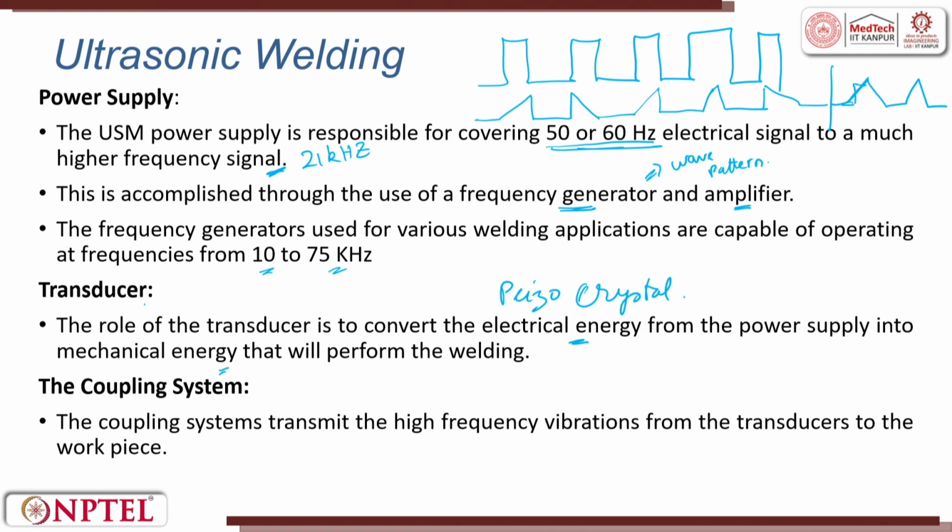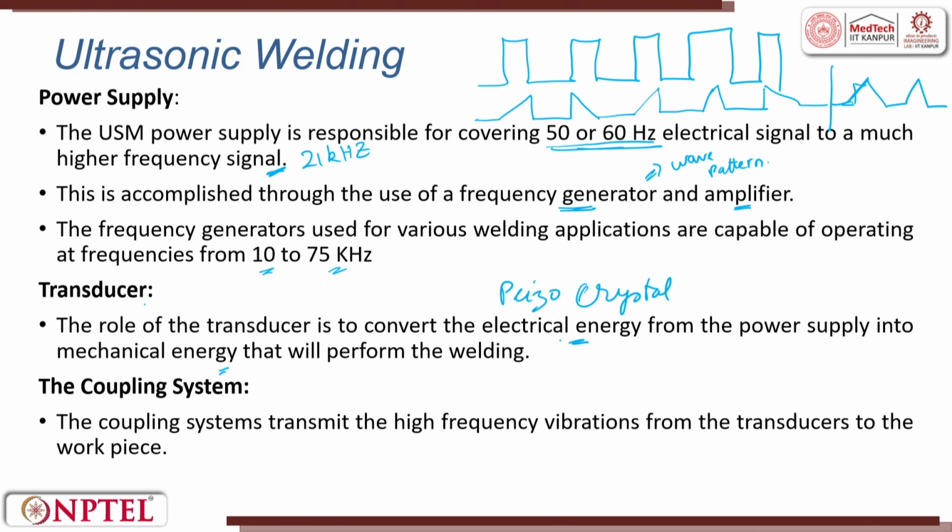The piezo crystal which is there. So, you apply voltage, it expands. Now the piezo crystal can be oriented in many directions. You can do it perpendicular, you can do it along, you can cut the piezo crystal at an angle, so that you get whatever you want. The same piezo crystal is also used for force measuring. In force measuring, mechanical is converted into electrical, here electrical is converted into mechanical.